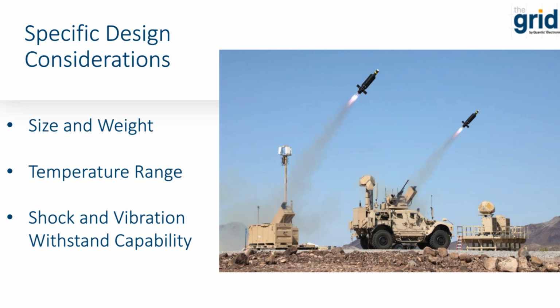Shock and vibration withstand capability is another key component. Many C-UAS weapons expose their onboard components to high levels of shock and vibration while being fired or while traveling to their target. Systems mounted on ground vehicles or aircraft are also exposed to notable vibration conditions during transit to the battlefield. Shock and vibration affect various capacitor technologies differently, so these ratings need to be confirmed during the selection process.